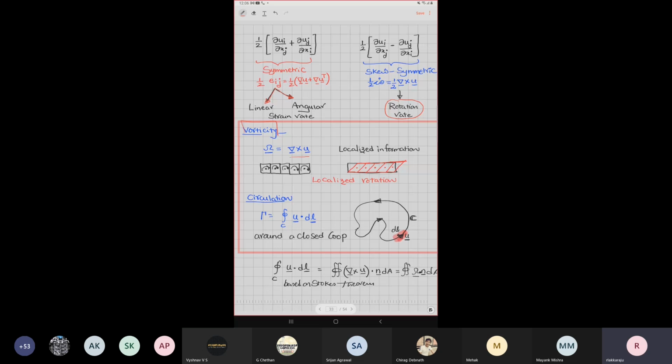Later we will see when we are learning about Newton's equation, Navier-Stokes equation and so on, this vorticity actually forces your fluid to go from one location to another location to develop into instabilities and turbulence. If I look at the microscopic view, you have a lot of complicated flow field. Pick tiny infinitesimal elements everywhere. Because we are on a Cartesian coordinate system, I always draw something like rectangles. You think of each of them as having some tiny rotation about its own axis.